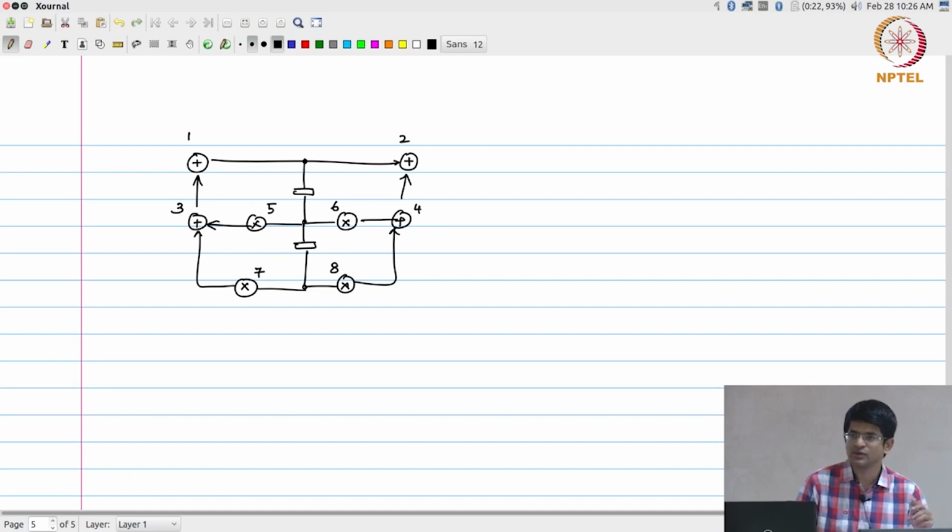Because as long as n is equal to 5, even if I reduce to 1 multiplier and 1 adder, I can get at best 80% hardware utilization, because there are only 4 additions and 4 multiplications. So the first question to ask is, can I bring n down to 4? In other words, can the critical path be reduced from 5 to 4?